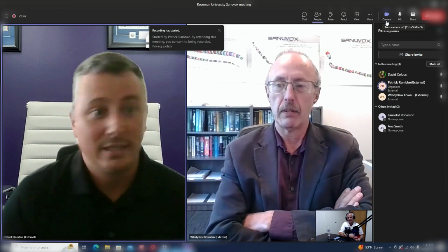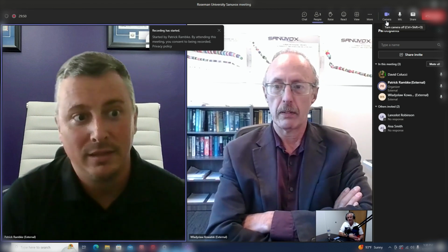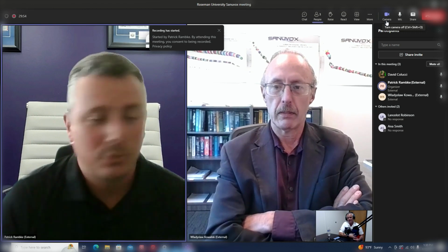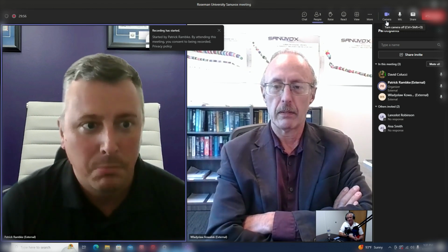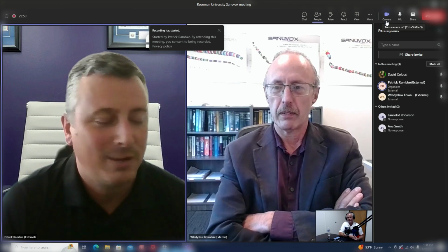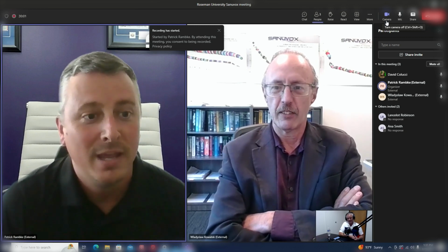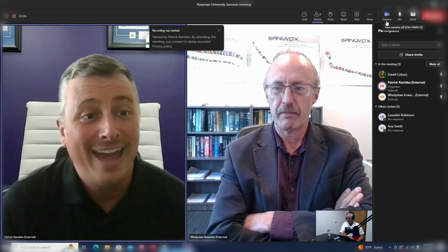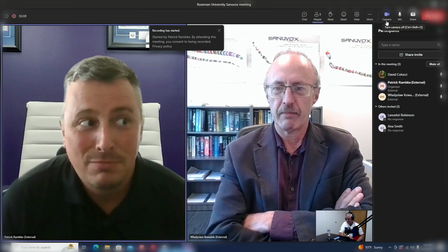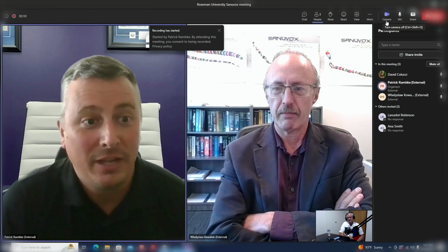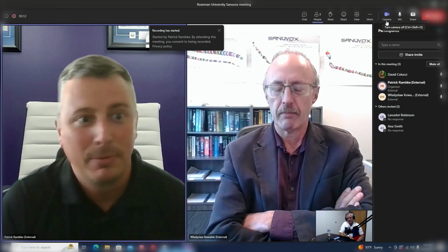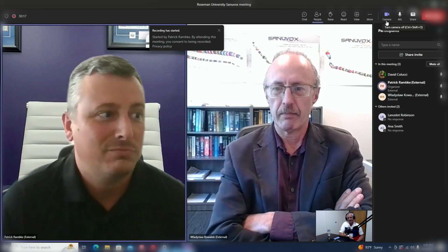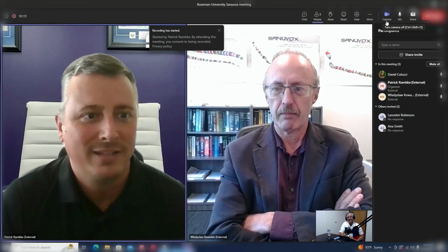Right. So states like California have severely regulated the amount of biocontaminants that actually can appear within the cannabis itself. Biggest one, Aspergillus niger. Everybody knows this one, black mold. If you've seen it sitting around standing water that's been sitting around for a while, it pops up. Yeah. It is extremely dangerous for people who have compromised immune systems. And this is something that is pretty much always around in the grow facilities just because they generally operate between 50 and 70% humidity at any given time. And that's just the ideal environment for bacterial mold growth.